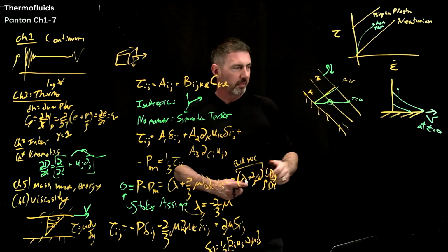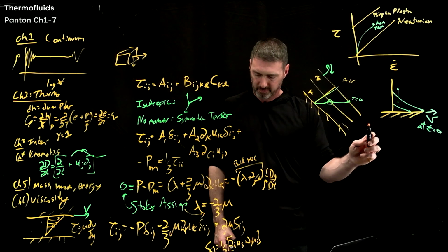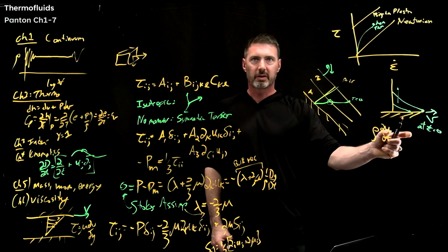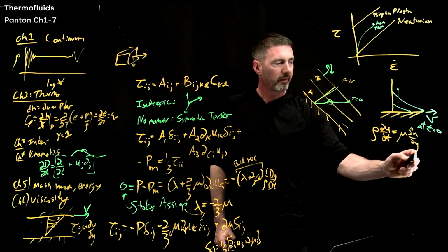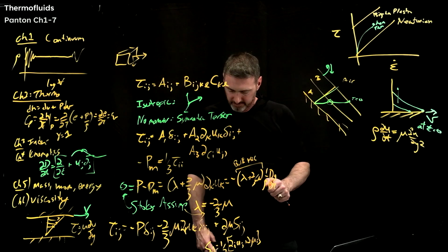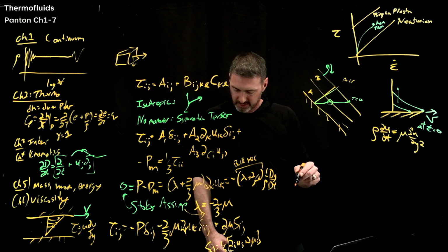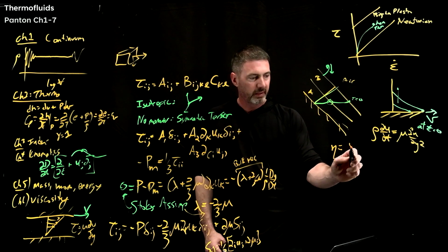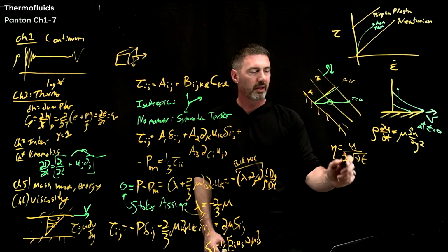And so when you go solve this, this is basically only the x momentum, and so you have rho, but the time rate of change still shows up. The cross term doesn't show up, and then you have mu times d squared u over dy squared. And so this is pretty neat. And you go through with the similarity variable, right? And in the end, the similarity variable, eta, you will write as y over 2 square root of kinematic viscosity and time.